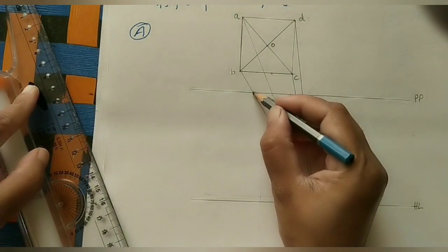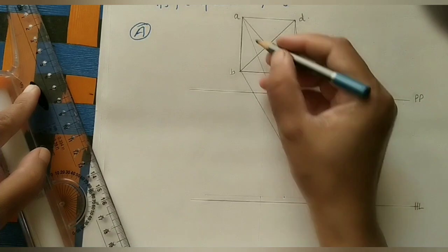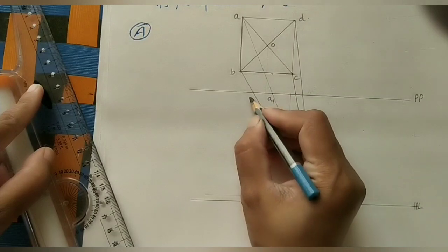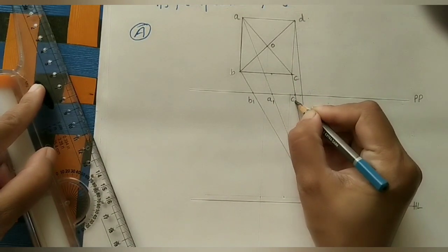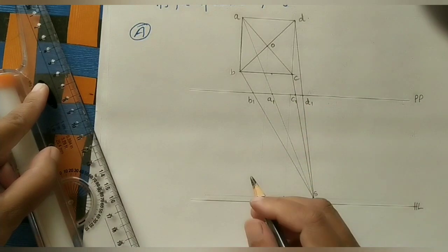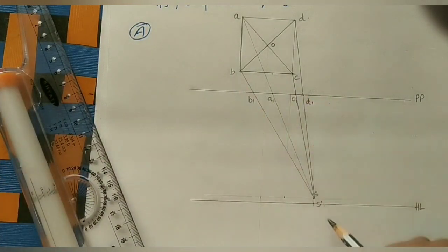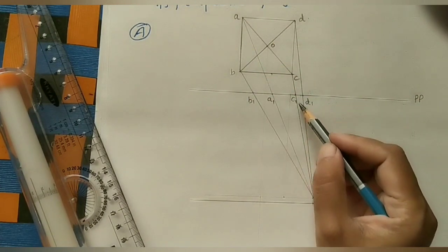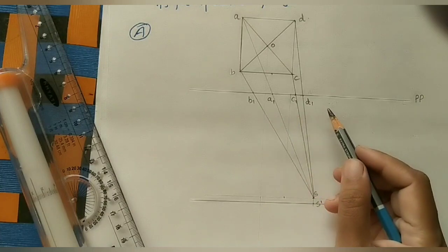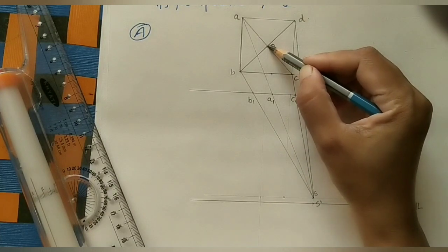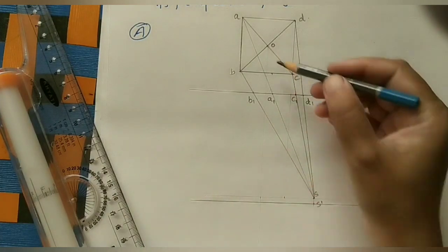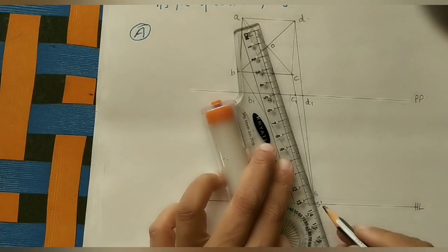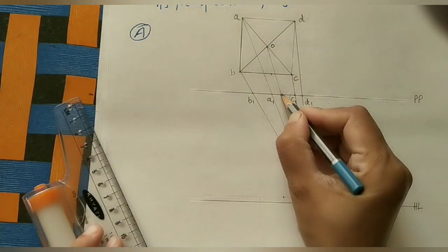Okay, here whatever intersection points are there, whatever A line will be there, I am taking that as A1. From B the intersection point to this line is B1. From C, this intersection point C1. From D, the intersection point D1. So I am taking the intersection points with these inclined lines to this PP line. From A, I am taking A1, from B, B1, C, C1, D, D1, like that. After getting all these points, join this center point to S also, because it is the apex. Join this apex to S. Like this. So name this intersection point also O1.